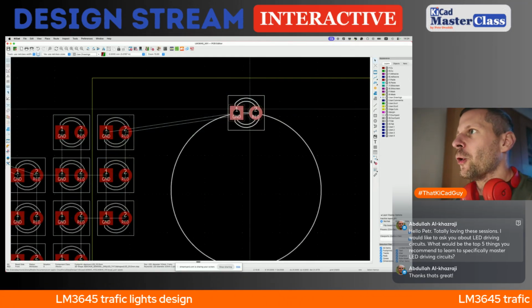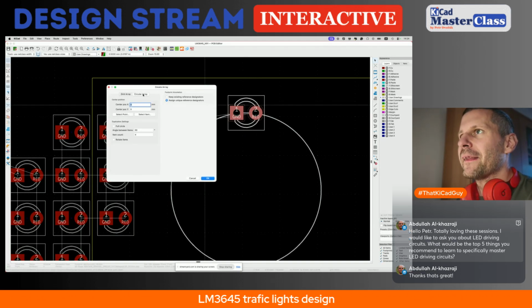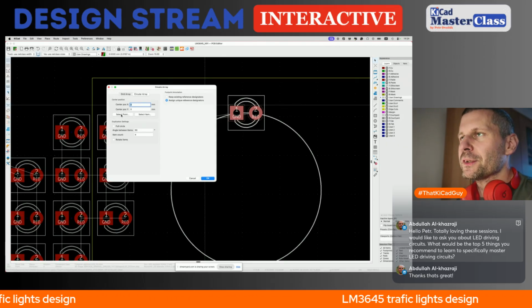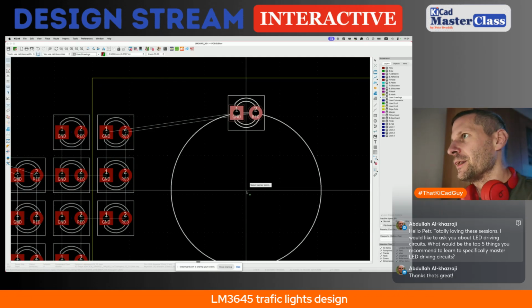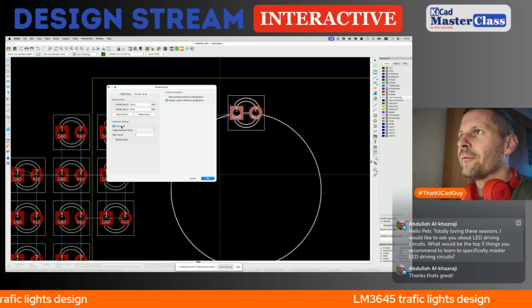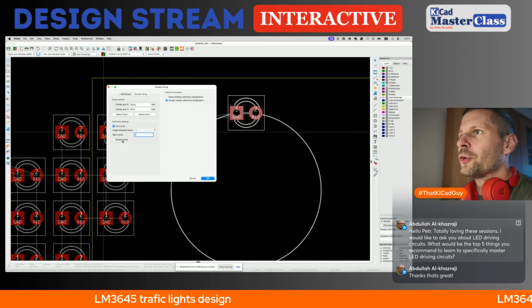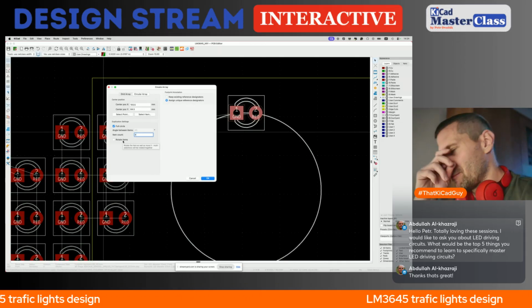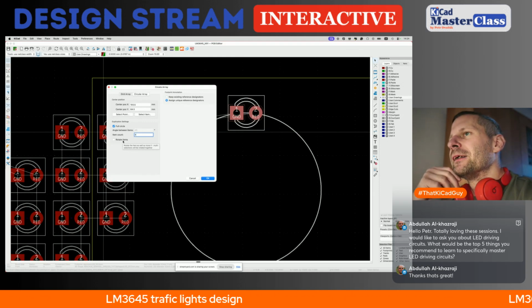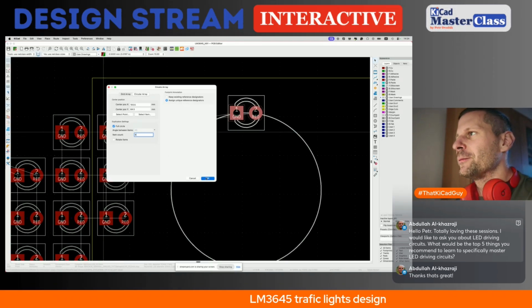Now I am going to use the create array from selection, and circular array is the thing. Center position will be the center of the circle. So this is our center point. We have to fill the full circle with 8 LEDs. And we don't want to rotate items because the LED is circular, so we don't need to mess with the position. Let's call it, and we will see what happens.